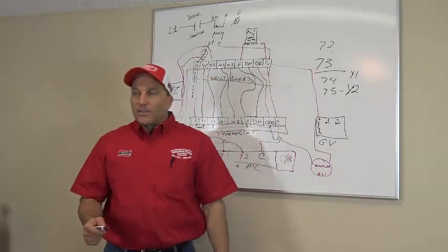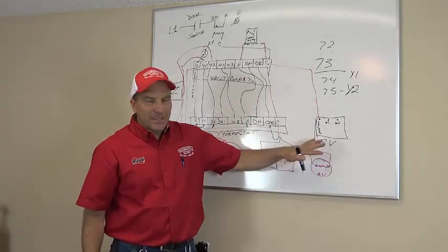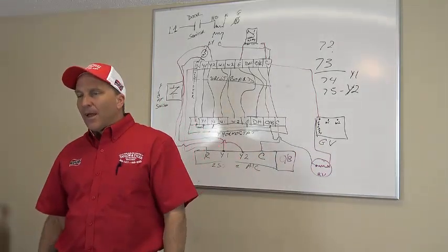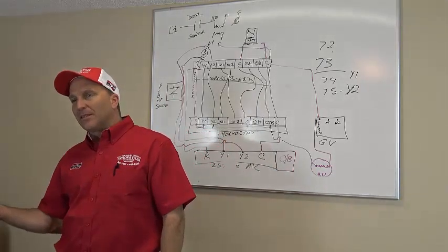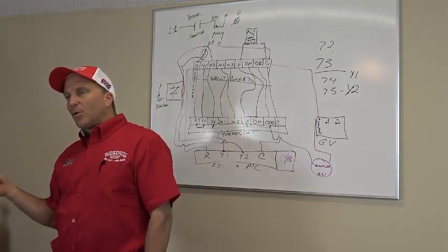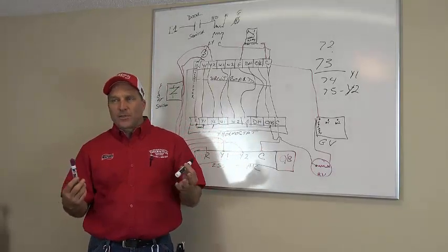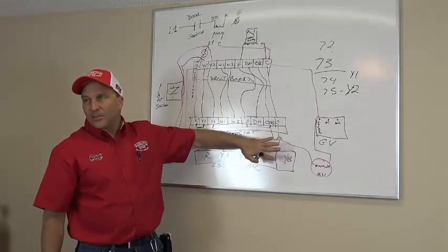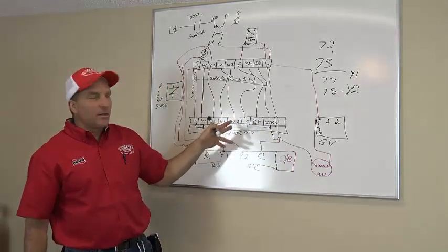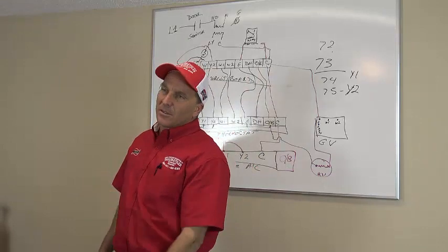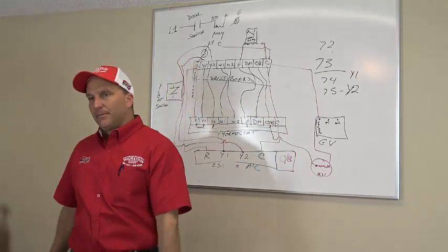Okay. Heat pump. Don't work like that though, does it? So a heat pump needs secondary heat. So when my heat pump gets too cold outside, then the heat pump no longer works. And there could be an outdoor thermistor that basically is telling you, hey, my outdoor temperature outside is too cold, so it can open up the circuit and no longer feed the air conditioning system in heat pump mode voltage. Then it tells the Y1 and the Y2, basically sending signals and saying, hey, I need for you to go ahead and turn the gas heat on because it's secondary heat.